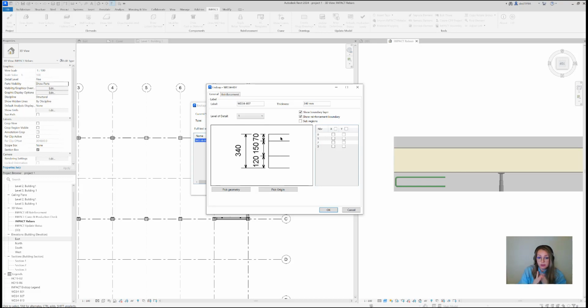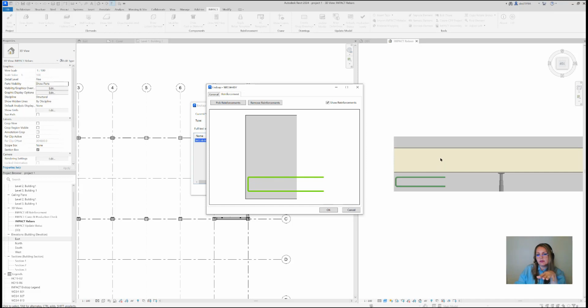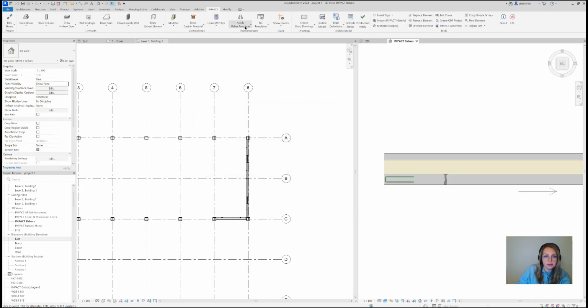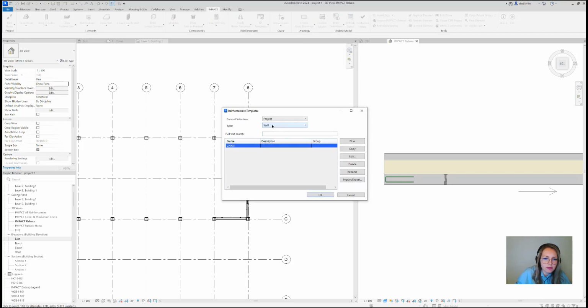Detail that is, notice, automatically added to the shop drawing when you create it to the production drawing. And the new thing here is that you can add this stirrup according to the insertion point, which is the lower left corner. And when this stirrup is added to the in cap, you can go in the reinforcement template. This is where we connect those two, reinforcement template and in cap, right? You can go to reinforcement template.